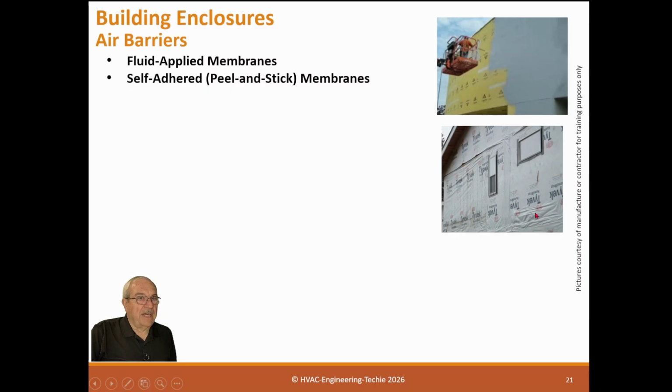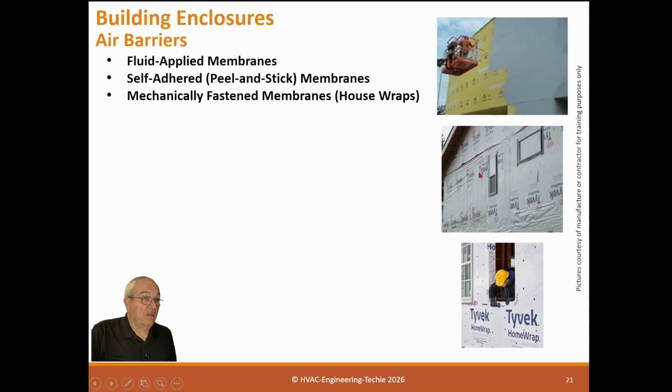And they leave sags, they leave gaps, they leave protrusions that are unsealed. And so it basically doesn't do a good job because of the way the installation's done. And another thing, if you get the back of this dirty, it no longer sticks. And I've seen that a lot, where down near the stem walls, it's coming off because it's not sticky anymore. So I'm not a fan of this, but it's used a lot.